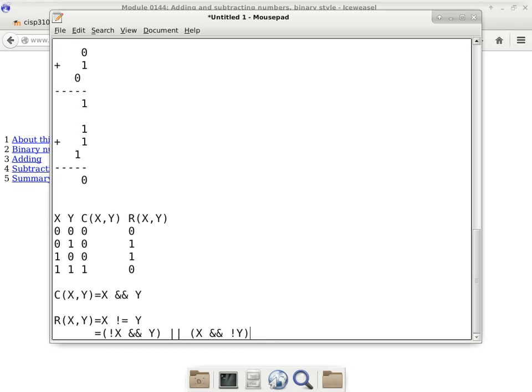On and off. For each operator that we are using, the regular conjunction, the regular disjunction, and also the regular negation, we already have a way to translate all of those into NAND 2 gates, right? And from NAND 2 gates, we have a way to implement that using 4 transistors. In other words, we know how to perform all of these operations using just transistors. Now, it's going to be a lot of transistors, but nonetheless, we can do it.